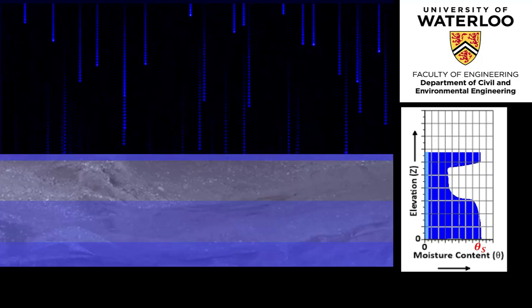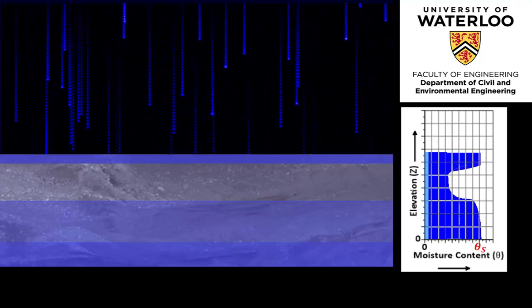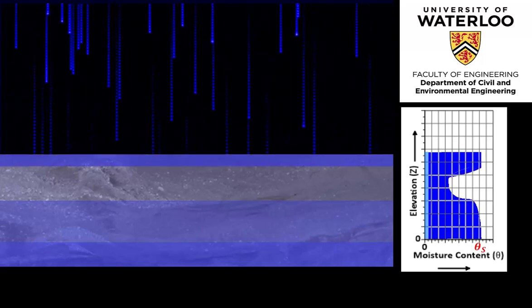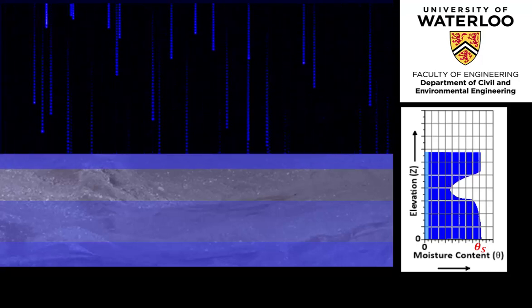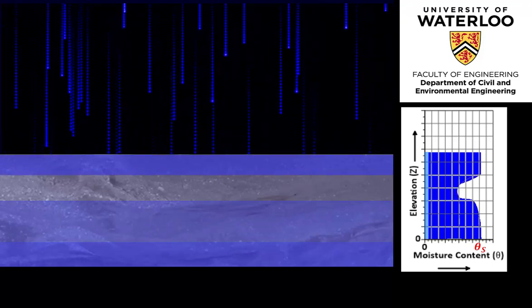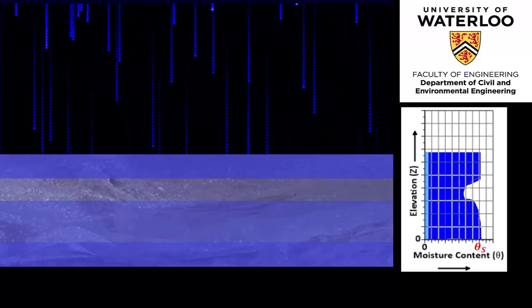This threshold and rate of infiltration is particularly relevant when partitioning a precipitation event in a hydrology investigation to determine the volume of water contributing to infiltration versus that of overland flow. It is worth noting that in most environments, a fully saturated soil profile from the ground surface to the water table will not be achieved over the period of the test. What is most important to evaluate is the percolation rate through the porous media, and thus the infiltration rate.